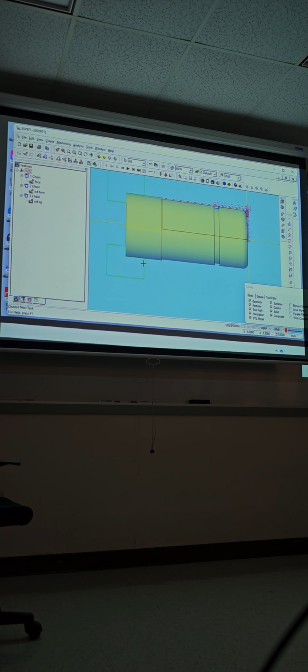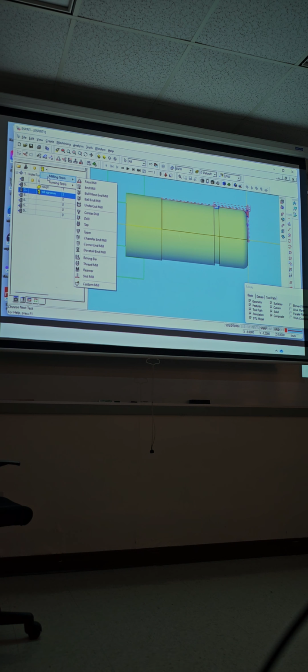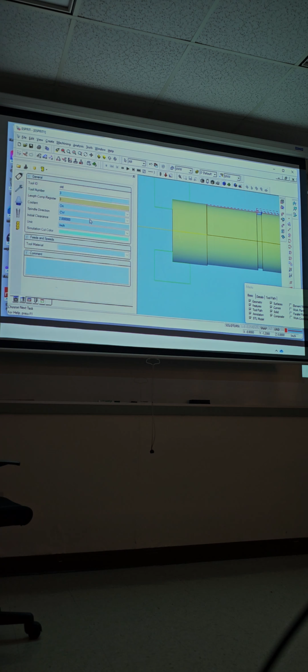All right. So remember, do we have drills in the mill? Yes. So let's go grab from the mill, but let's remember that we are stealing a tool from the mill, from the access point of view, okay? So here, sometimes I confuse when I'm talking. So let's go tools, right, over here. Instead of going turning, we're gonna go to milling. So after we go to milling, we're gonna go to drill.